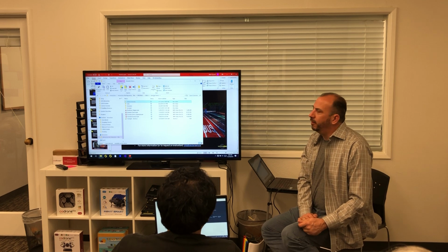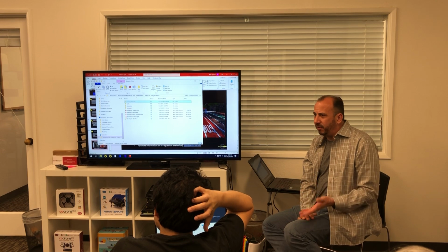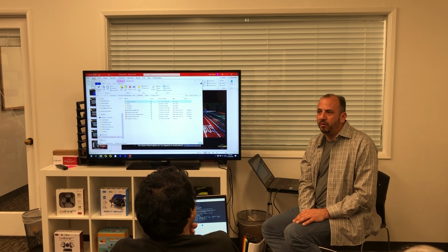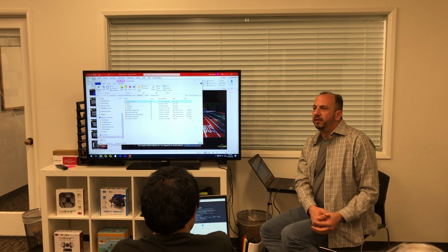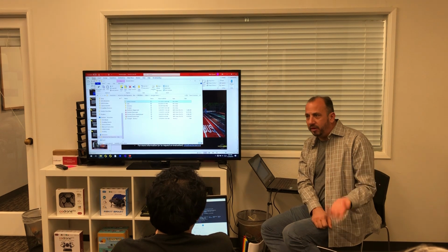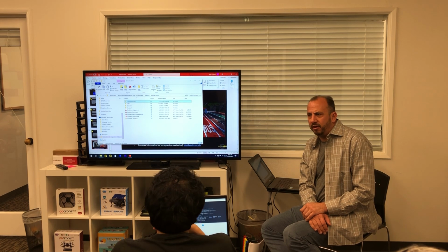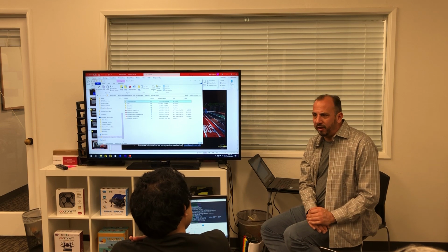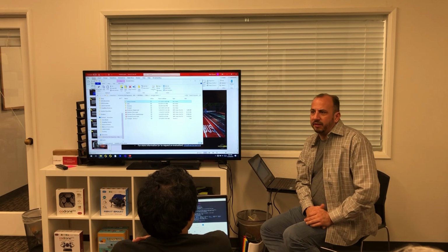And so we'll typically start with a bunch of GIS data. So we'll start with aerial imagery, we'll start with an elevation map, which might often be at 10-meter resolution, which is pretty coarse. Near the coast, you can get 1-meter resolution elevation data, which is pretty good. We'll bring in whatever data we can. If you're near the coast, you can usually get good LiDAR data because I guess the Coast Guard does LiDAR scans of the coast to do flood modeling and flood preparedness. So all that data is available. So yeah, there's a bunch of map data sources available.